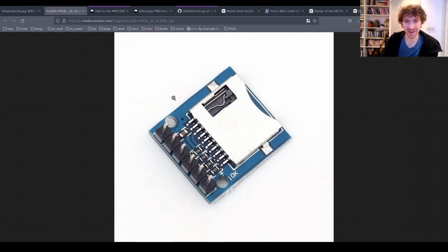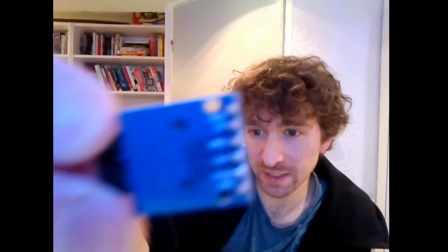What you'll notice here is we've got the SD card entrance, we've got the pins. There are a couple of resistors there. Those are 10K resistors. They kind of look like they're in line. It's hard to see the traces in the circuit there, but don't worry too much about it. This is what's on the back. It's basically blank. You can see there's some silk screen that says the pin names, and you can't read them because my camera just absolutely refuses to comply.